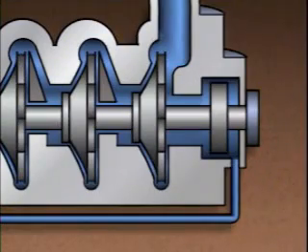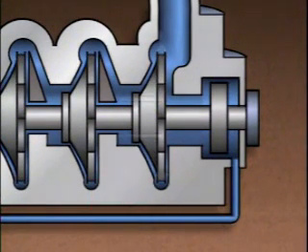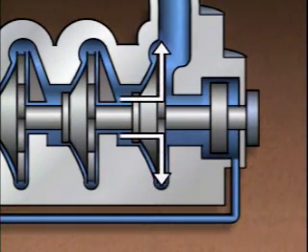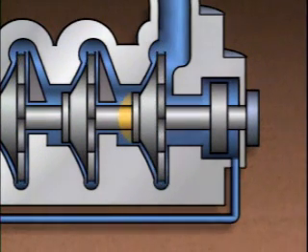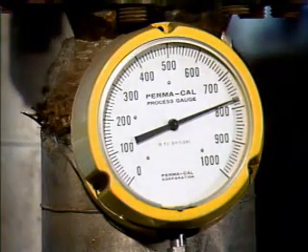Three common flow path classifications are radial flow, axial flow, and mixed flow. In centrifugal pumps that have a radial flow design, the impeller causes the liquid to make a 90-degree turn and flow outward, or radially, from the suction eye to the tips of the vanes. A radial flow pump takes advantage of the maximum amount of centrifugal force that the impeller develops. Generally, radial flow pumps are capable of higher discharge pressures, but they don't move as much liquid as other types of centrifugal pumps.